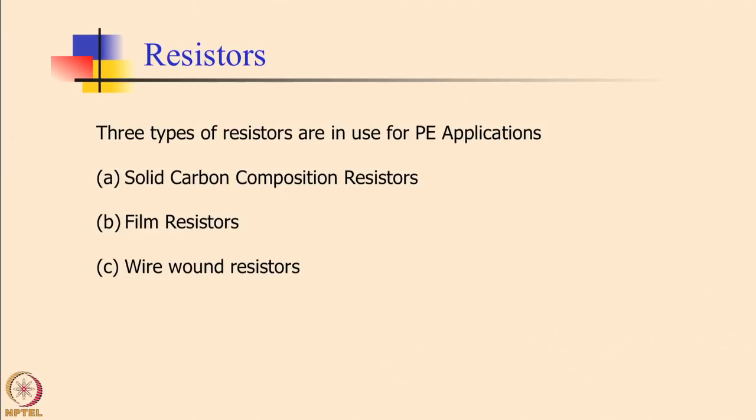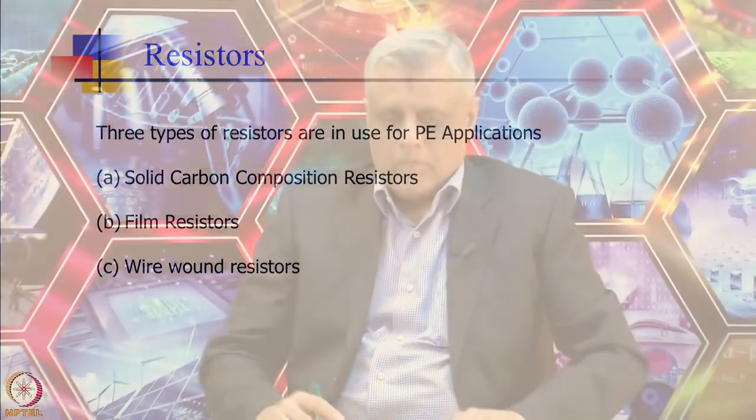One of the specialities of nichrome wire is that its resistance does not change much with changing temperature. The wire wound resistors can give an accuracy of around 5%. Another issue with wire wound resistors is that they also have a large parasitic inductance. Therefore, they cannot be used in applications where the parasitic inductance might be a concern in the working or the measurement.